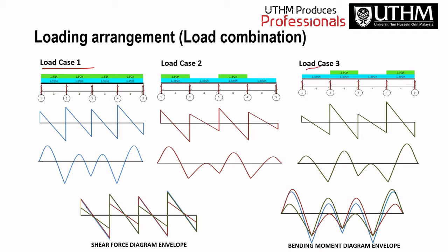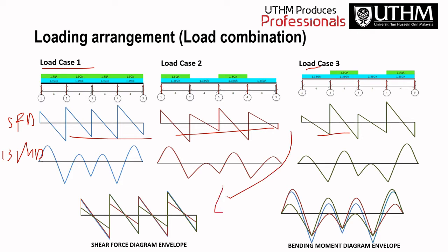Okay, so you need to draw this SFD, and this is the bending moment diagram. So you draw all these three, you combine into this, and you draw these three, you combine into this. So this is the envelope for the shear force diagram, and this is the envelope for the bending moment diagram.